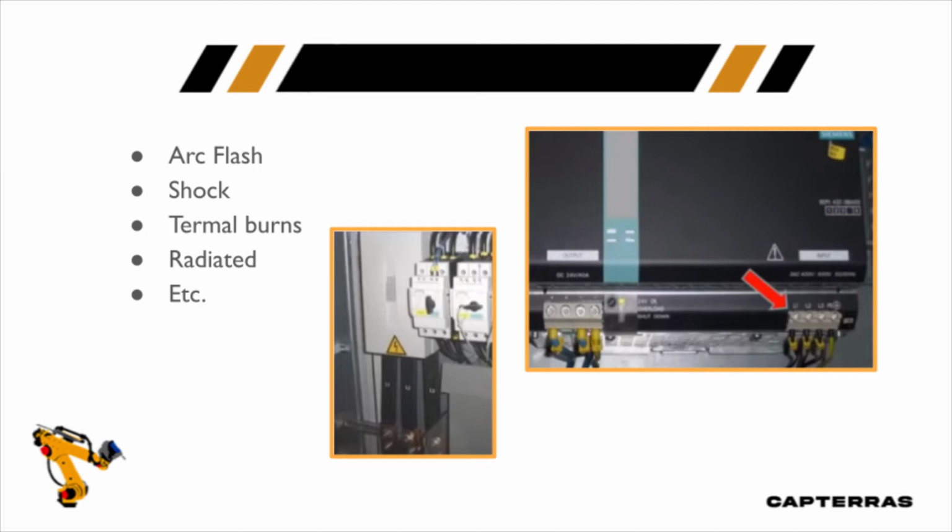On the lower left there, you see a site where you have a plastic cover. Now, this plastic cover may help protect against someone making direct contact from a shock perspective, but if something falls down behind that cover, we can still have an arc flash event. So our risk assessment would tell us it's still very important for us to provide arc flash protection.